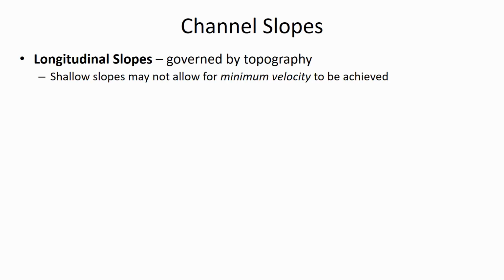Are particles settling down to the bottom of the channel? But there's an additional concern as well. In sewers, since there's no light underground, we don't have to worry about weeds growing. But in an open channel, there is the possibility that a really slow-moving water would allow unwanted plants to begin to grow. And then there's a whole lot of maintenance that goes into mowing the grass that can grow in the channel and keeping cattails at bay, and especially in water bodies that have lots of nutrients in it, like nitrogen and phosphorus, then the vegetative growth can really get out of control.